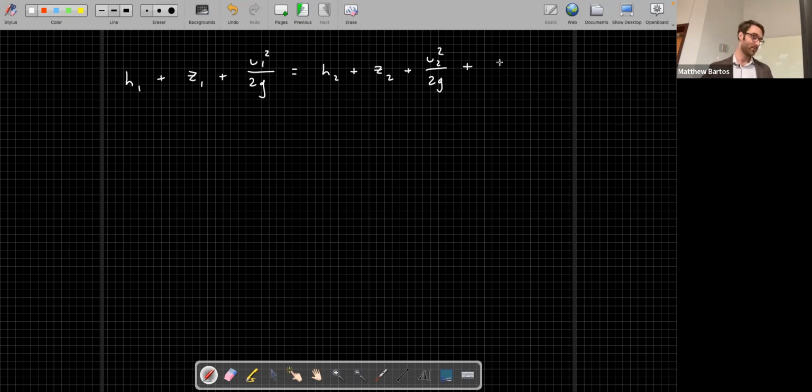And we also have head losses. What do you think those head losses incorporate? What do you think the major head losses are there? Right, the frictional losses. So that includes the frictional losses. What else does it include? Losses from the transition.